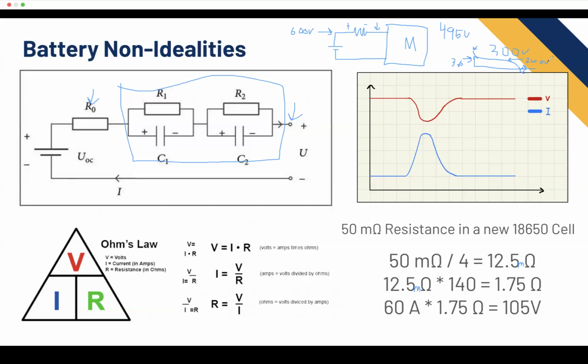And oh, you press the accelerator too hard and that drops to like, what, 135 volts. And then the inverter browns out. Browning out is when you lose power. Right, blackout would be like if you turn it off. Brownout would be when you pull too much power so it shuts off. So the motor would shut off because it would be like, hey, the high voltage system isn't charged high enough. It's not safe to be doing that anymore.